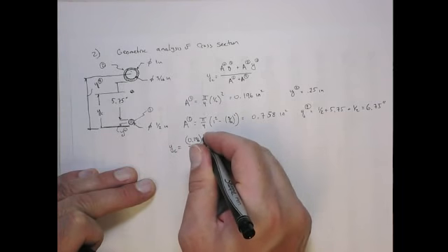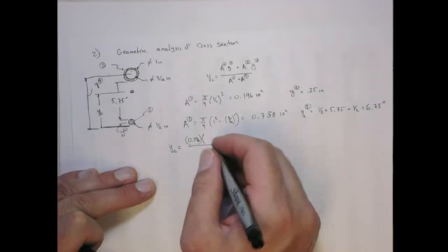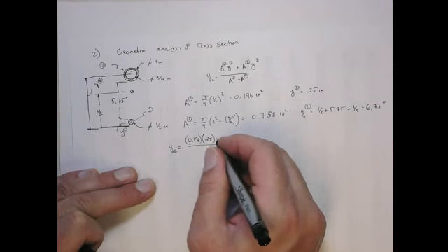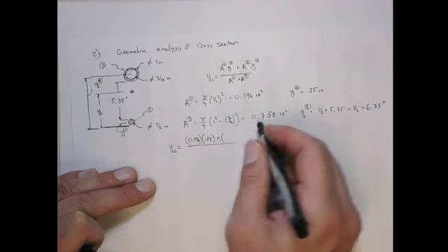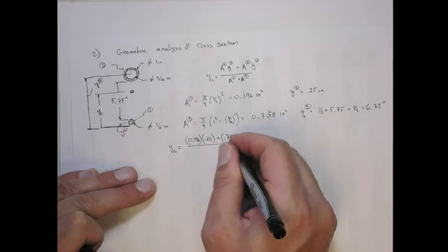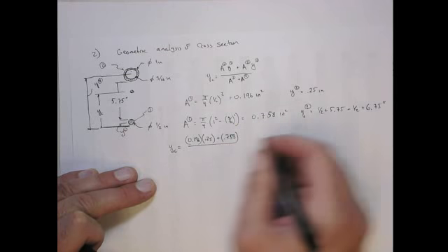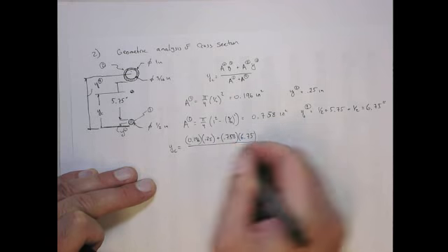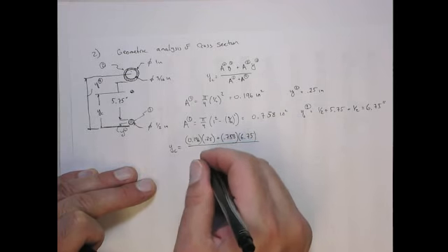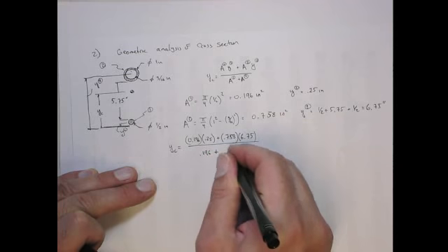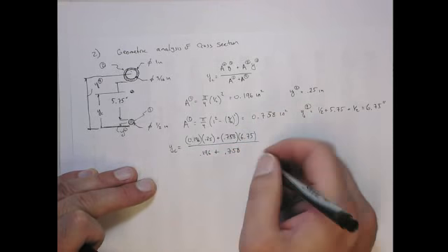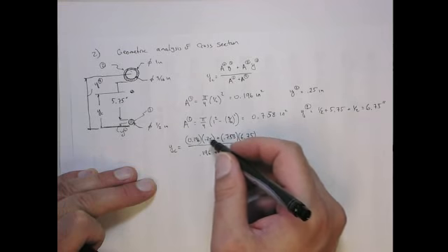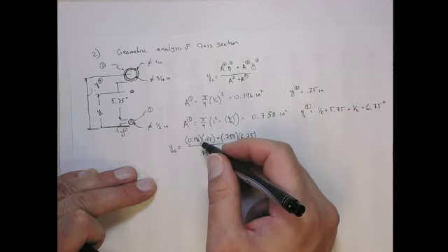So now that gives me that YC is going to be 0.196 inches squared times y1, which is 0.25, plus the second area, 0.758 inches squared, its centroidal distance, 6.75, over the total area, 0.196 plus 0.758. So this is inches squared times inches, that's inches cubed.